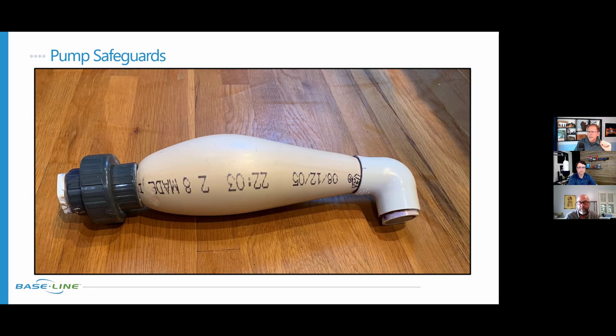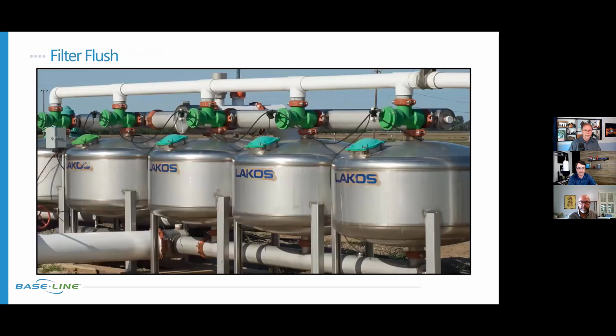I think we mentioned the other day, for a relatively modest fee, you can add just the pressure component, and you can upgrade your old pump. The computing power is already there in the base station 3200. So we're just going to add the pressure input, and now we could prevent this from happening. Now, scale that up from 1.25 inches to a 4-inch or 6-inch. That's pretty serious. And you actually have that, right, Dan?